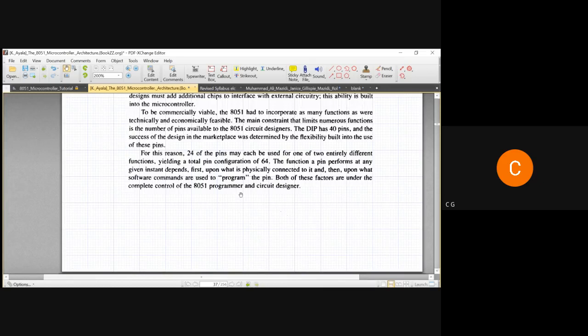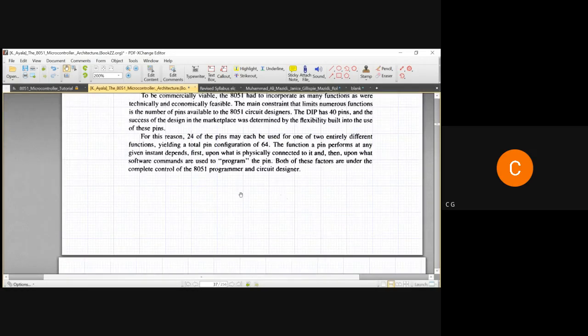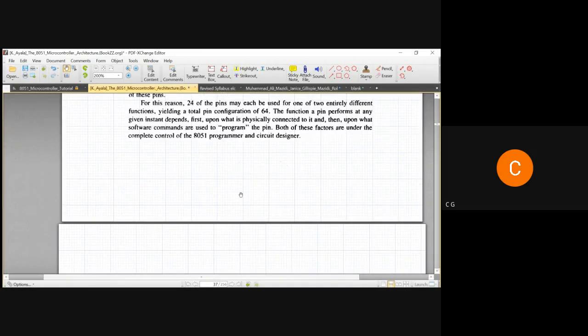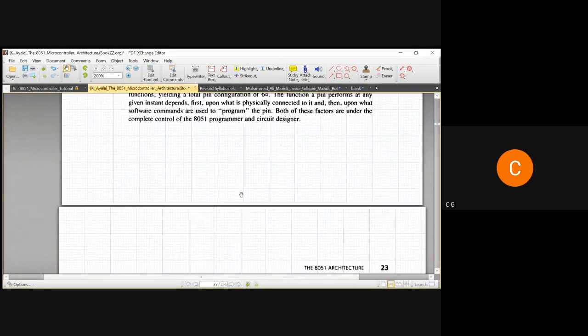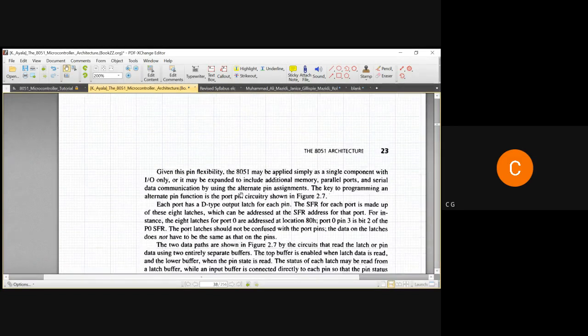Even though it is 20 megahertz frequency, 20 divided by the machine cycle will tell you the maximum number of operations it can perform. So 20 megahertz divided by 8 clock pulses, that will be the value you obtain for the number of operations this microcontroller can perform.